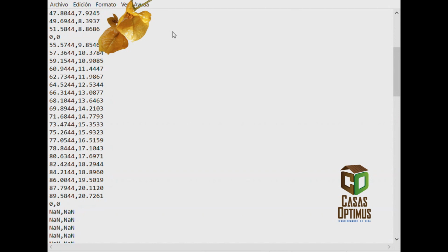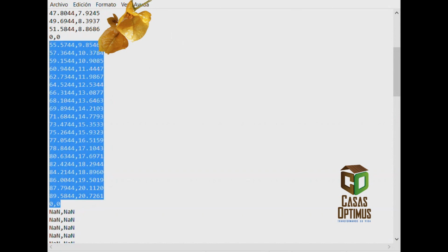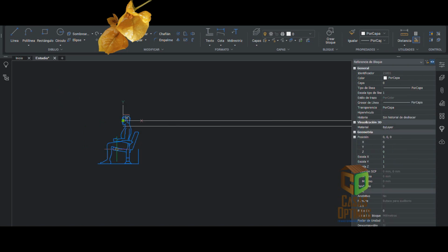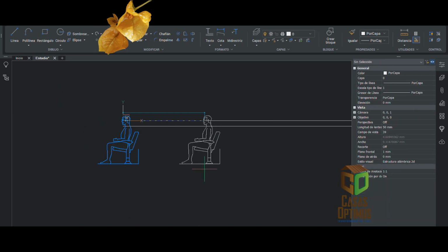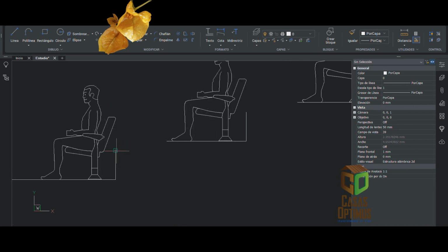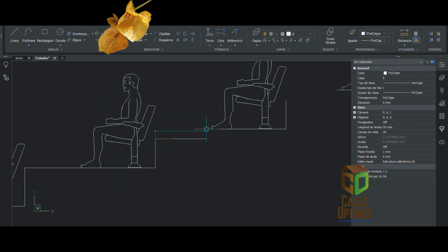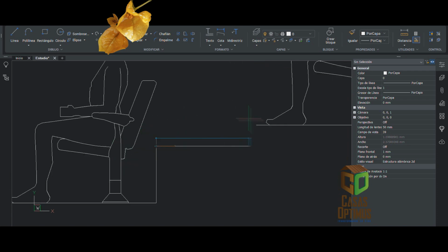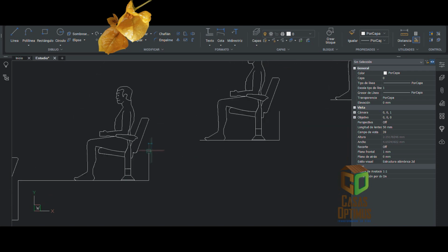Now just copy and paste the coordinates into your favorite drawing program. By pasting the coordinates with the origin in the center of the eye of the seated person's block, you will have practically the second level, and it is only necessary to complete a few lines. When you're checking the isoptics and row spacing of this second level, everything on this second level will be perfect.